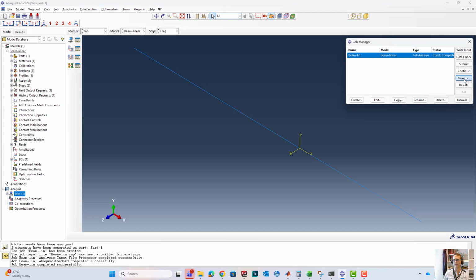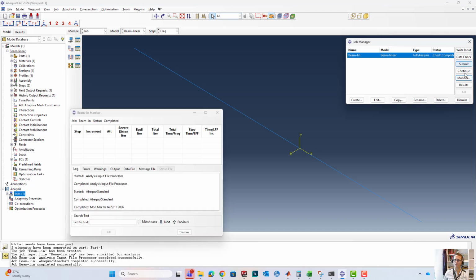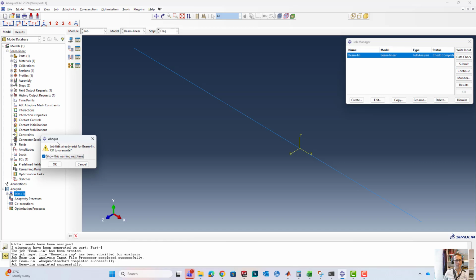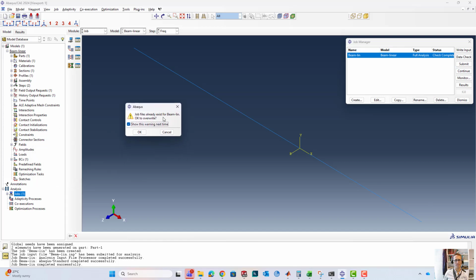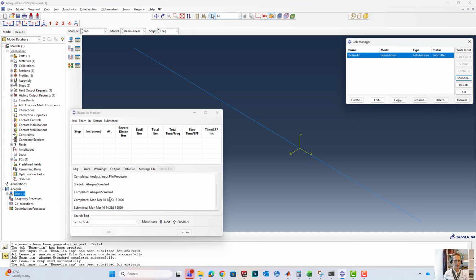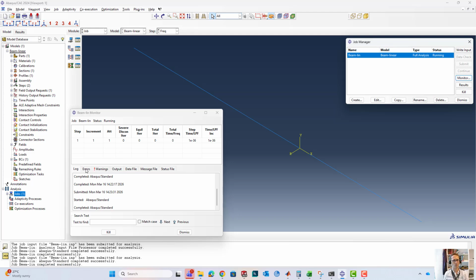Now if I go back here to Abaqus, rather than hitting submit after a data check, I can just say continue. It's going to say there are some job files already that exist here. Are they okay to overwrite? Particularly it's creating a new output database. Yes, that's okay, because I know that the things it's looking to overwrite are simply the results of the data check, which doesn't contain any actual useful information. So I will say OK, and away it goes. It continues now to solve this problem for the 25 frequencies and shapes that I've requested it to solve for.